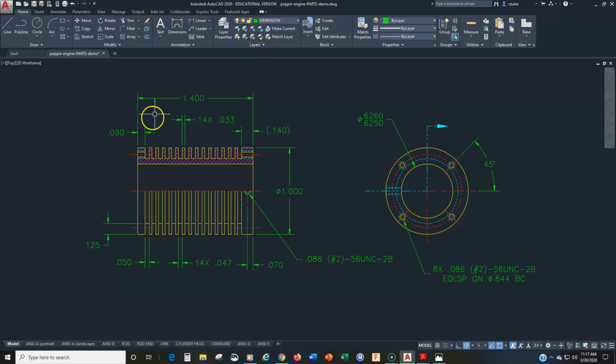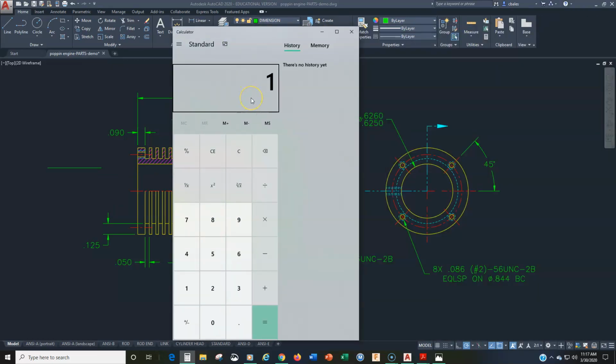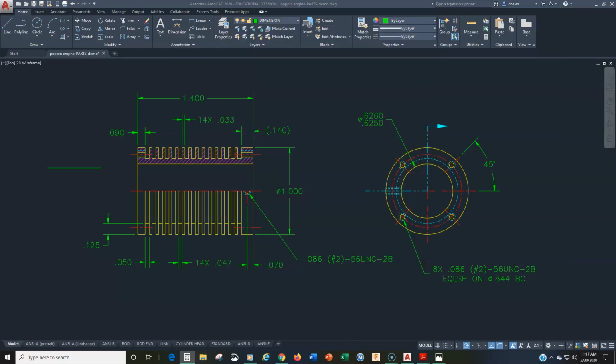We're going to draw it on the dimension layer because it is a dimension feature. So I'll draw it right there, right? And then I'm going to offset that line, and I'm going to offset it 1.5 times the text height. The text height is 0.125, so I'll show you how we do that. So it's going to be 1.5 times 0.125, which is 0.1875, right? So I'm going to go back here and offset 0.1875. I'm going to offset it once and twice.